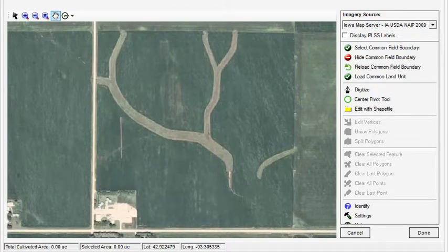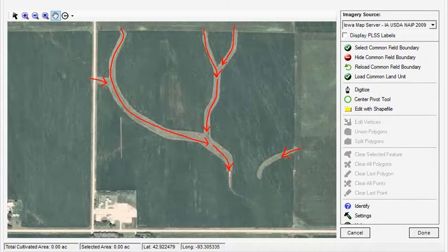In this tutorial, we're going to look at how to approach removing complex, uncultivated areas. When you run into situations, such as seen in this field, where many uncultivated areas branch in from various places and converge, don't attempt to digitize and remove the boundary all at once. You will more than likely double-click the mouse button somewhere in the process, and this interior polygon is too complex to fix when that happens. Instead, remove the uncultivated area piece by piece.